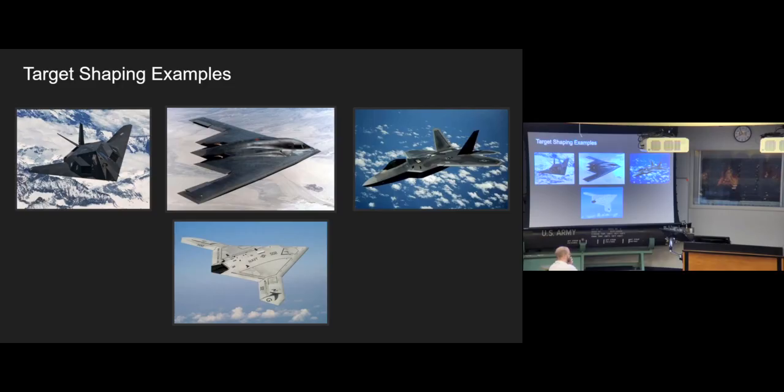And an important thing to note, radars are often on the ground. Remember that I mentioned that inlets are horrible? Radar cross-section? Notice where the inlets are on the stealth vehicles. They're above, on top of the vehicle. The inlets on the B-2, on top of the vehicle. The fighter couldn't do that one because it needs to be fast, so it sacrifices some stealth there. The drone, the inlet's up here.